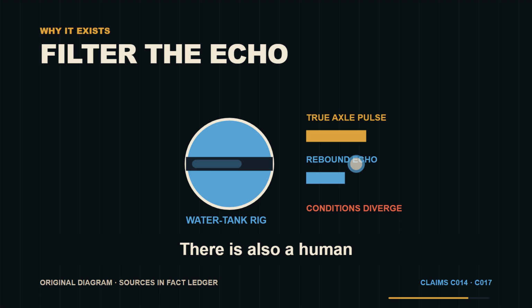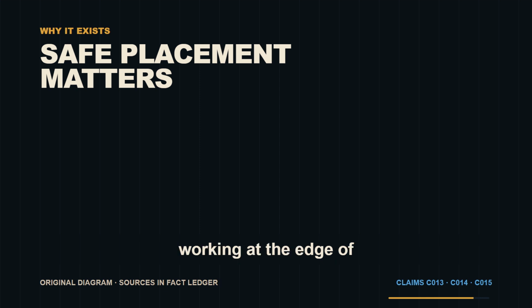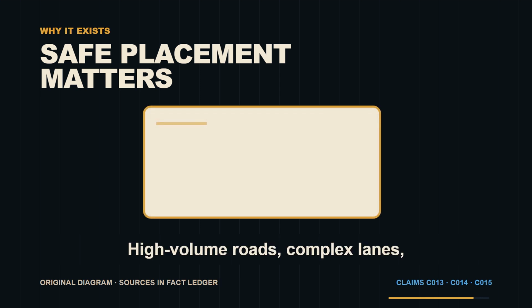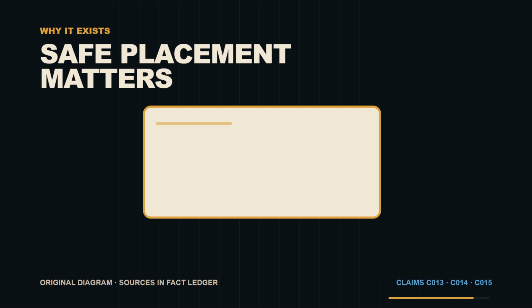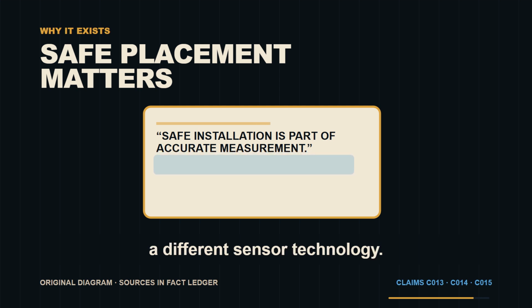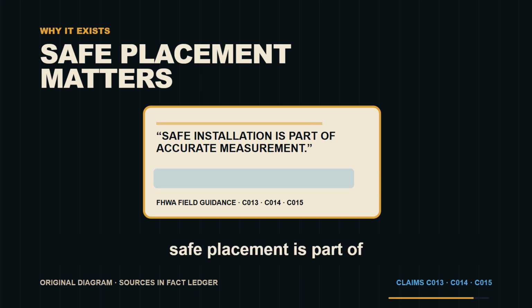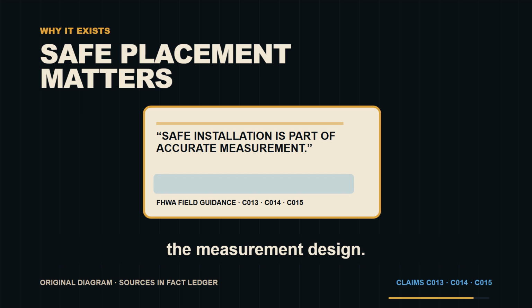There is also a human limit. Installing and securing tubes means working at the edge of moving traffic. High-volume roads, complex lanes, poor pavement, or unsafe access may require a different sensor technology. Temporary does not mean casual. Safe placement is part of the measurement design.